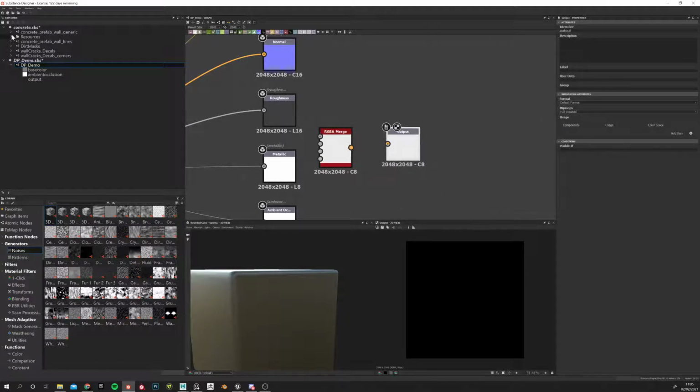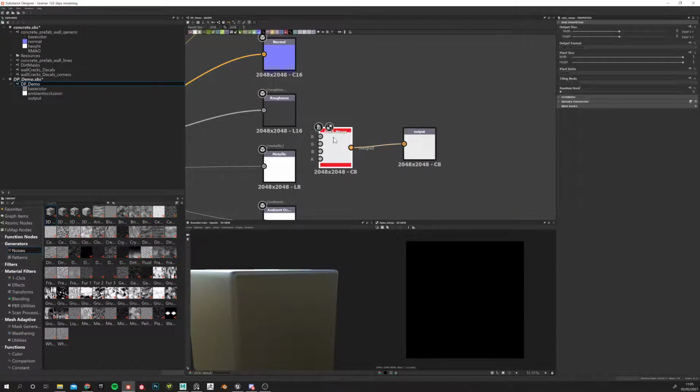In fact, every time you put one, you see it automatically. Look, I call one base color, one ambient occlusion, and I have another one I call all output. If you open this, you see I already have all this stuff as an output. I can take one of these, drag and drop it in here, and make a connection to that, because it's part of the same project. So I'm going to connect this. If I double click, at the moment it's black because the alpha is 0, so there's no color and no connection.